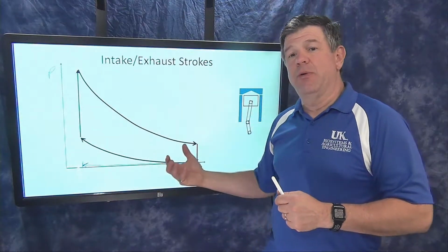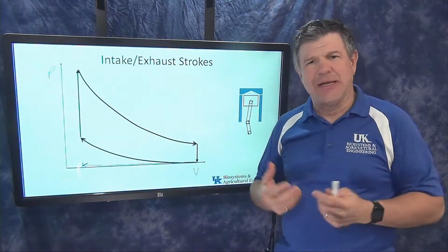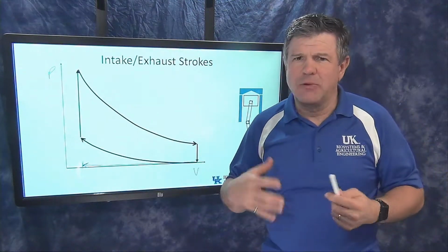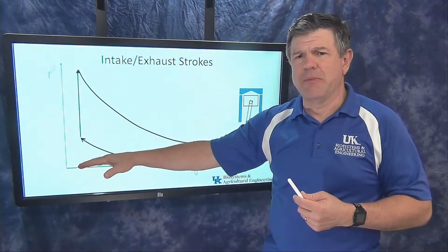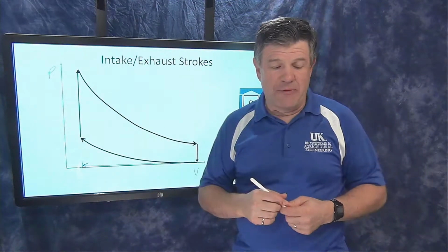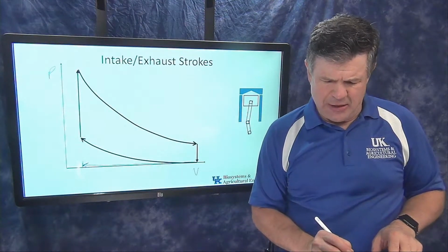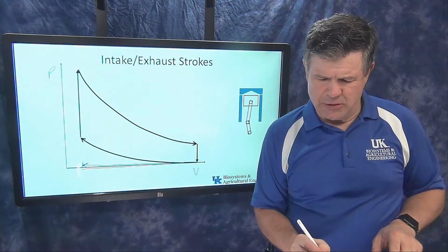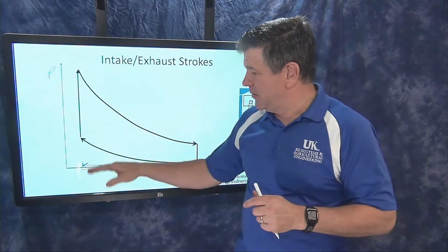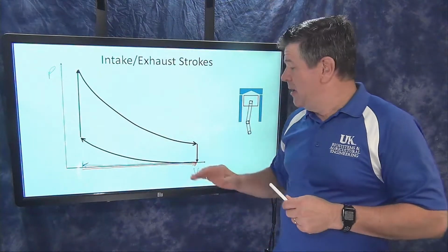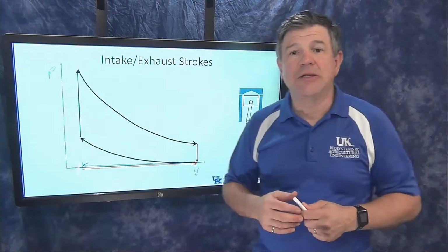Now what happens when I pull back in, so my piston moves back down this way? It's going to be pulling in some gas. Now is there going to be a vacuum there? Yeah, and we'll look at that in just a second, but theoretically, relative to these pressures, it's not very much of a pressure difference. So that curve actually comes right back along there. So what I'll do is change the color just to show that the intake stroke then comes back along. They should both be right on the x-axis, and I have a little separation there so you can actually see them. So the blue line is my exhaust, and the red line is my intake stroke going back and forth.